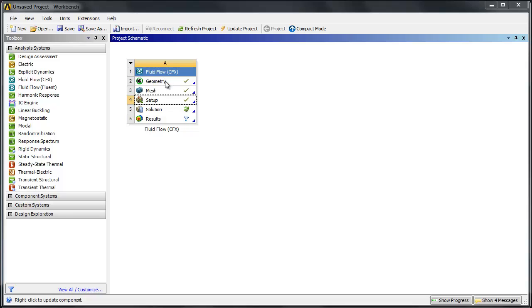We now have a defined geometry. We've broken that geometry into a mesh with several nodes at which we wish to solve for temperature. We've set up the domain and the boundary conditions. All these things now result in a set of simultaneous algebraic equations that have to be solved. Somehow the matrix has to be inverted to solve for the unknown temperatures. And that's the purpose of the solution cell. We will double click on cell 5, which should open the solution program.